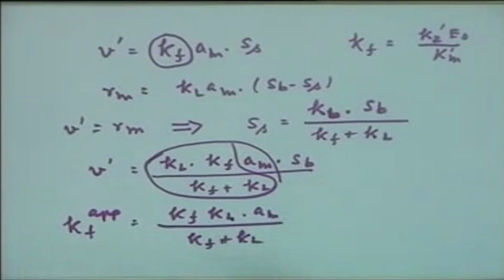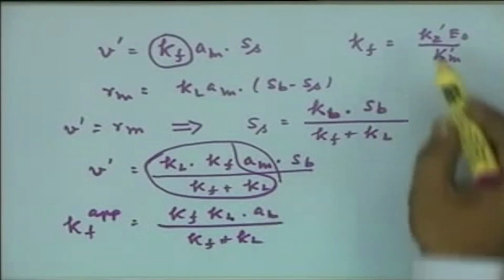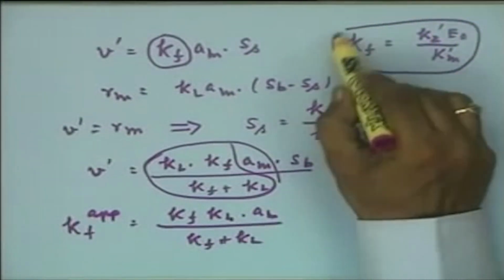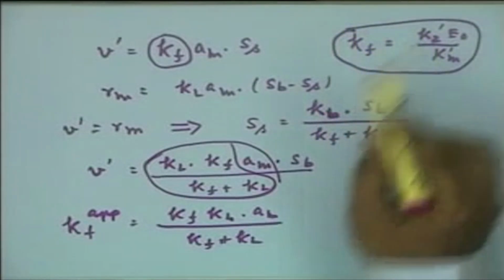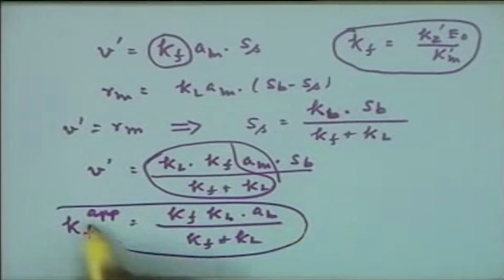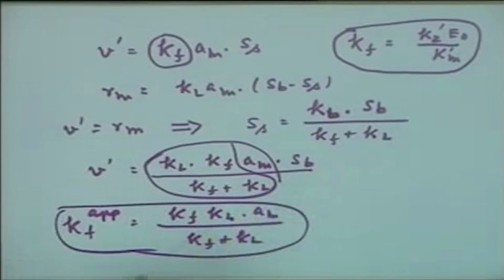So, in your reactor design equation, instead of a first order rate constant based only on the biochemical reaction, you incorporate this value. And of course, as I mentioned, Kl can be determined either from your experimental data, from the Lineweaver-Burk plot, or from your empirical equation of the Jd factor.